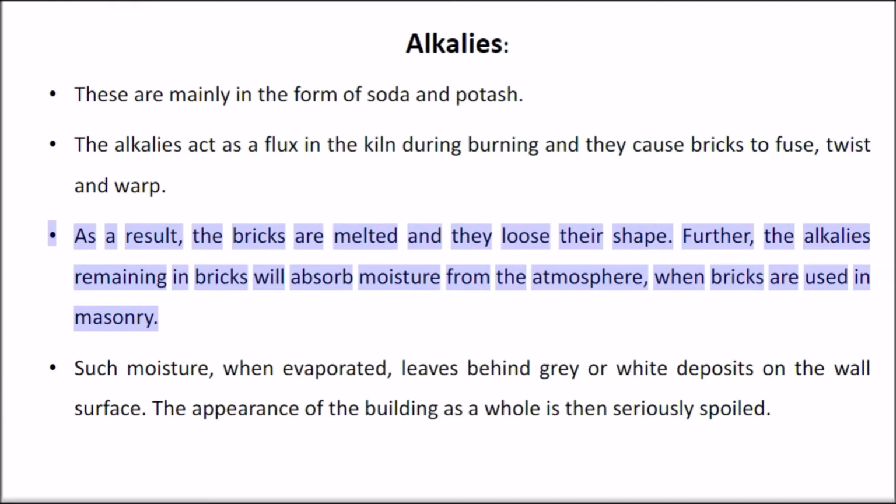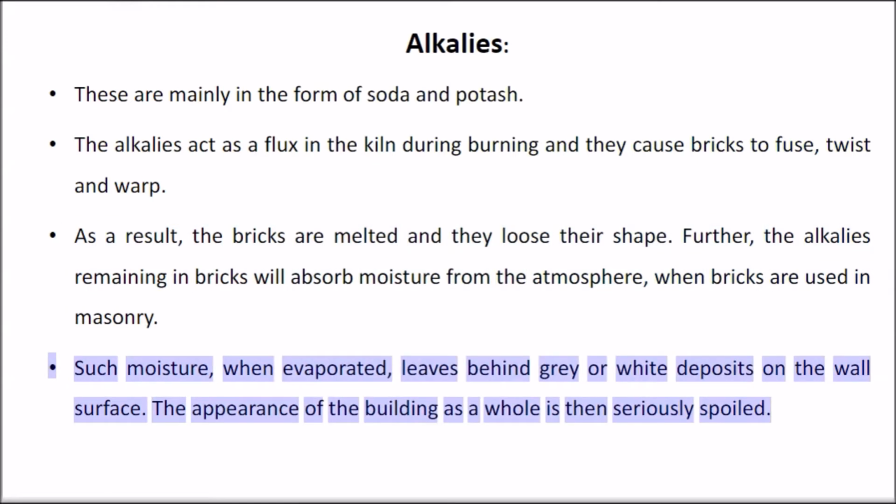As a result, the bricks are melted and they lose their shape. Further, the alkalis remaining in bricks will absorb moisture from the atmosphere when bricks are used in masonry. Such moisture, when evaporated, leaves behind gray or white deposits on the wall surface. The appearance of the building as a whole is then seriously spoiled.